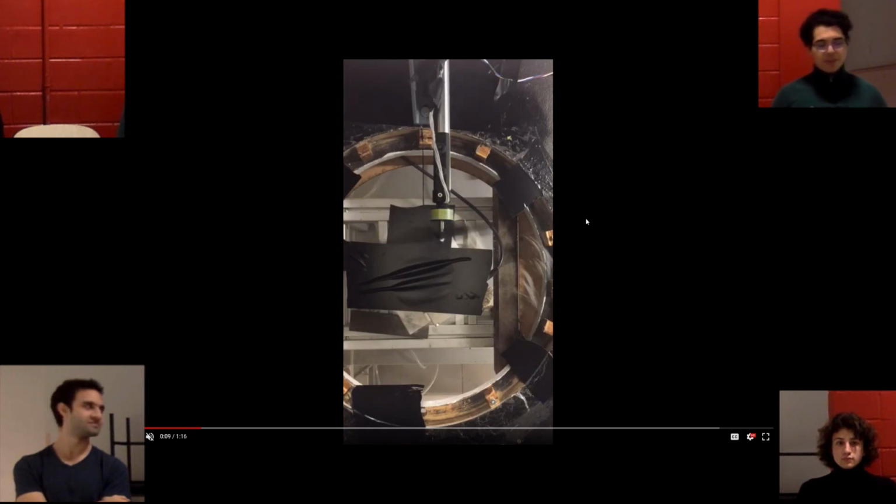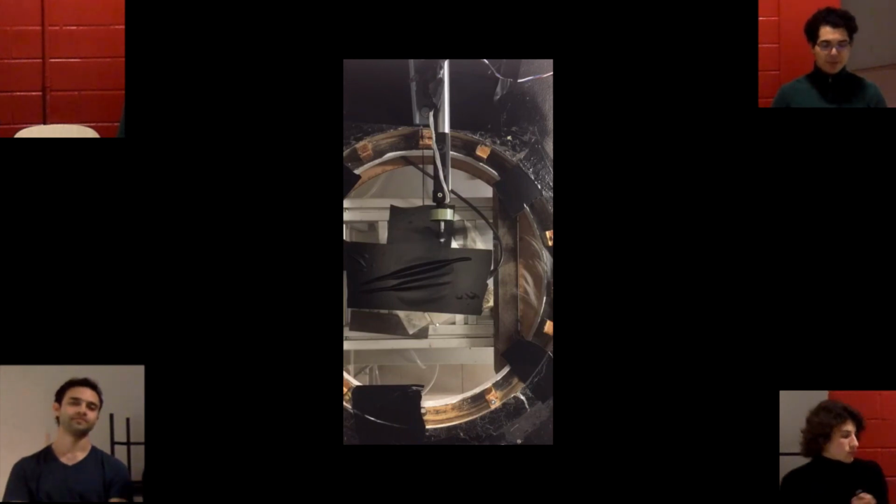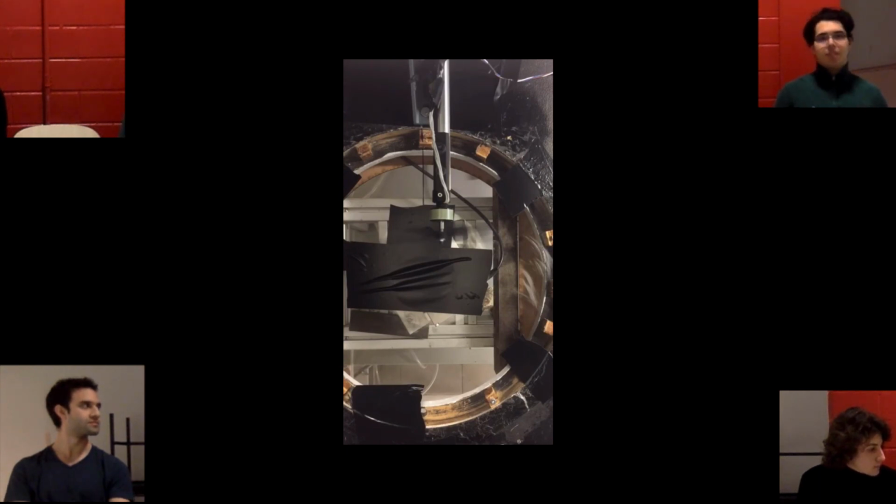So in this video we can see the propeller actually functioning in the air tunnel. In this test we can see fairly well certain misalignment in the mounting of the propeller. We're thinking that this probably induced more noise and vibrations than would otherwise have occurred, which obviously affects efficiency and the ability of the thruster to work without causing noise in the thrust curve, which is reflected in our results.